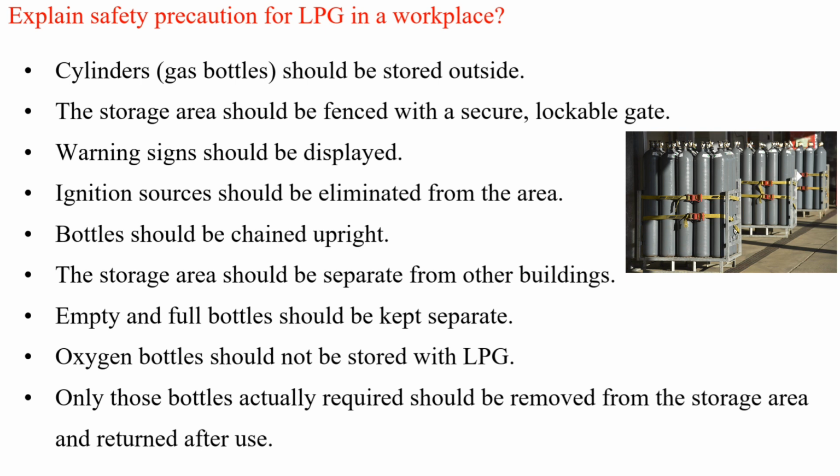Explain safety precautions for LPG in a workplace. Cylinders, gas bottles, should be stored outside. The storage area should be fenced with a secure, lockable gate. Warning signs should be displayed. Ignition sources should be eliminated from the area. Bottles should be chained upright.